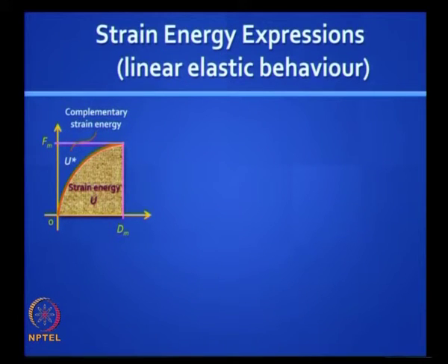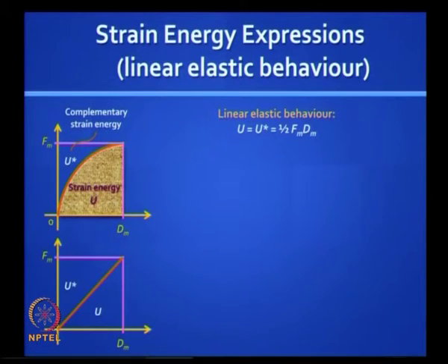Now let us talk about linear elastic behavior. In fact that is what we will deal with most of the time unless you have non-linearity. The beauty in linear elastic behavior is these two terms are interchangeable. U is equal to U star is equal to half the maximum force times the displacement, and what we need in structural analysis is how to compute strain energy and complementary strain energy in beams and frames and trusses and torsional members and so on.